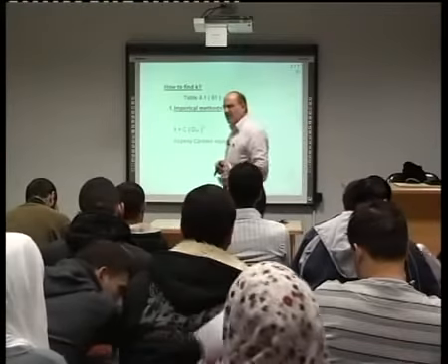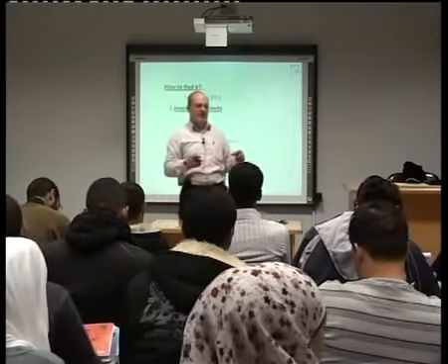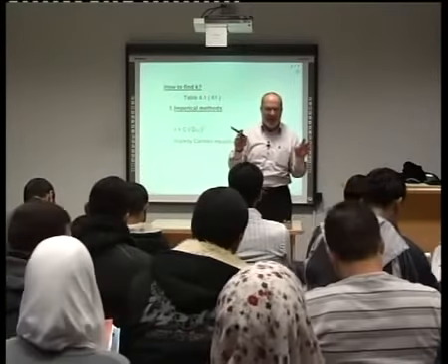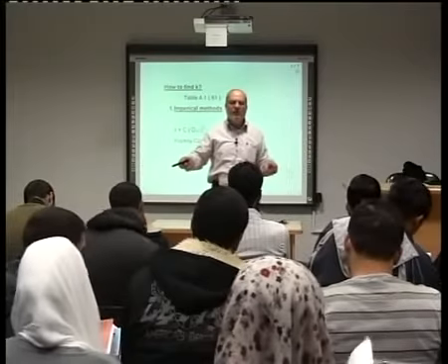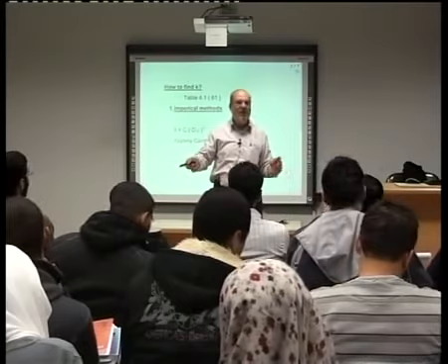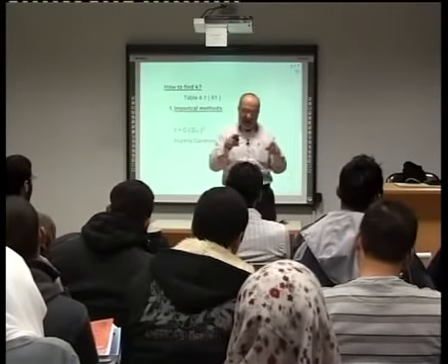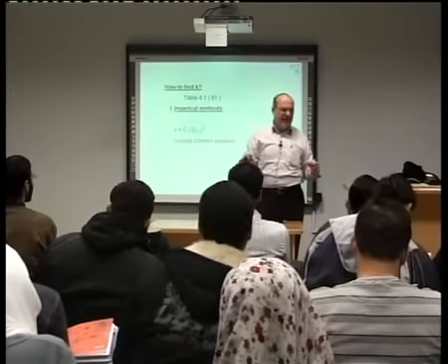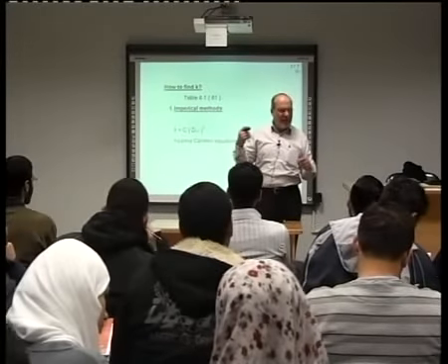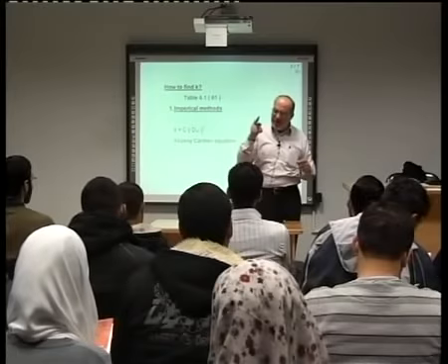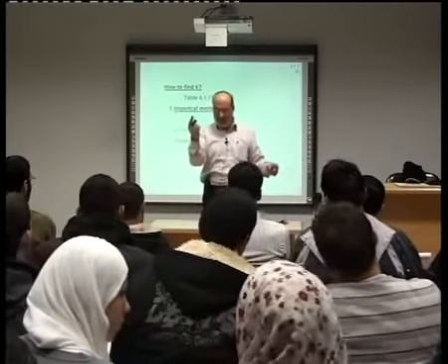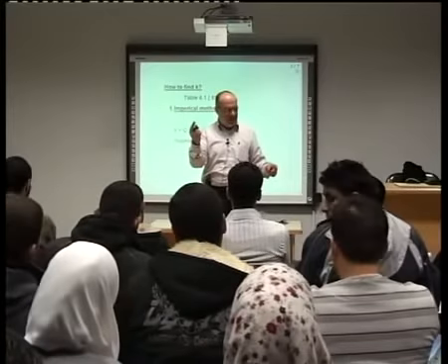Just to have an idea, let me compare between two figures. If we have clean sand, okay? Clean sand. So K may reach 1 meter per minute, even 1 meter per second, okay? Are you with me? K in clean sand, or gravel, which is permeability, may reach 1 meter per second, means that water can go through the soil 1 meter per second. Okay? This is K.